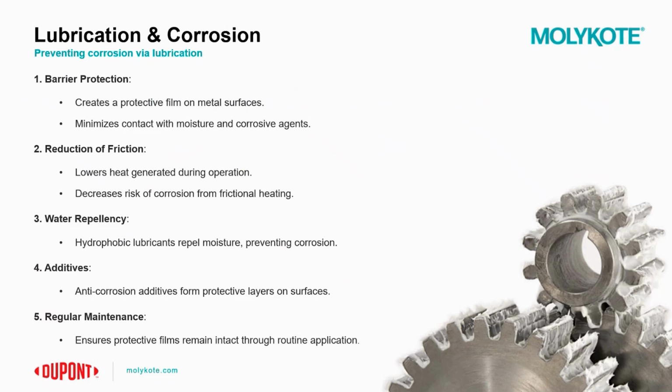Additionally, the lubricant can also help with moisture displacement. There are certain lubricants that have properties that allow them to displace moisture from the metal surfaces, again reducing the likelihood of corrosion. Chemical protection is another thing that lubricants will provide in a corrosion mitigation application, because a lot of lubricants contain additives that provide additional protection against corrosion. And what these additives really do is they neutralize the acidic contaminants, or they provide a sacrificial layer that corrodes preferentially, ultimately protecting the surface that you're lubricating. So the base metal, really.